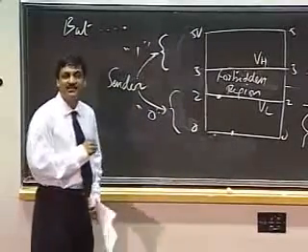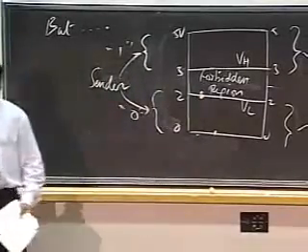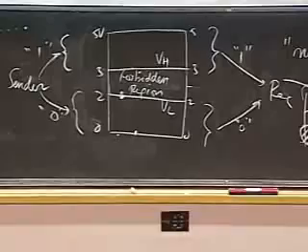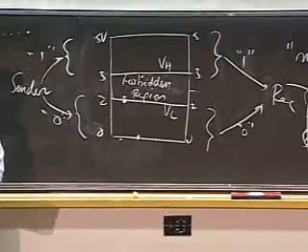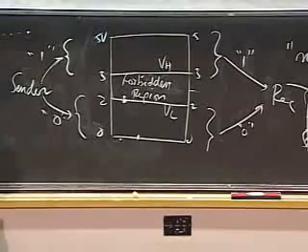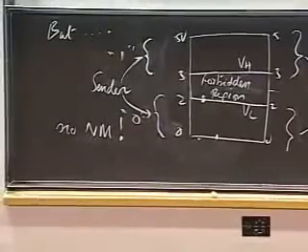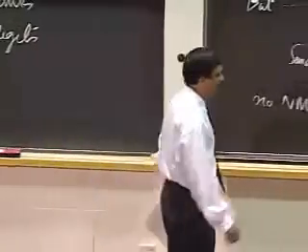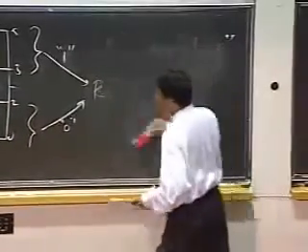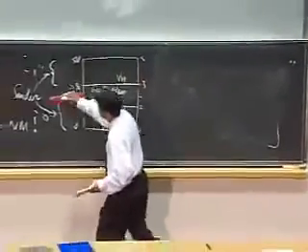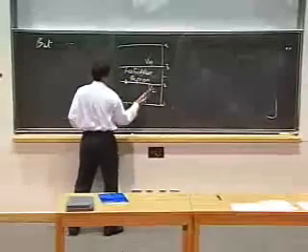This way I can make really cheap parts. But now the problem is that even the smallest amount of noise will bump it into the forbidden region, and so therefore this one has a problem. And the problem is that this one offers 0 noise margin. There's no margin for noise in this discipline. All right, back to the drawing board, folks. Switch to page 8. Okay, let's get rid of all the stuff and go back to the drawing board.